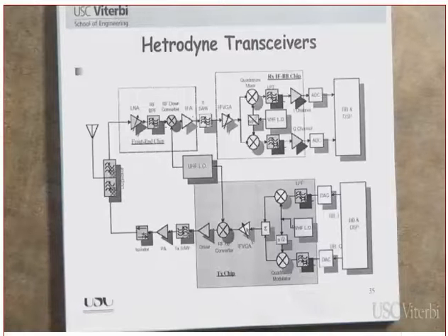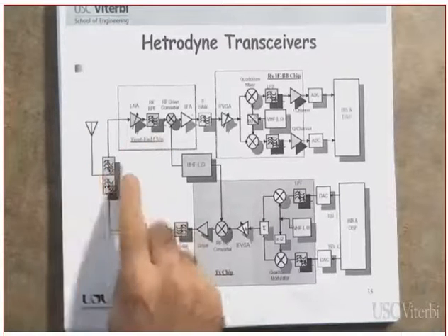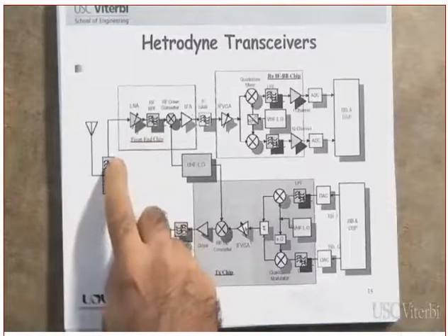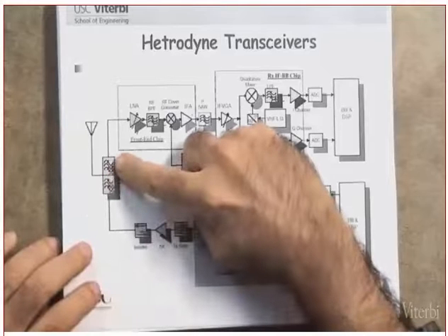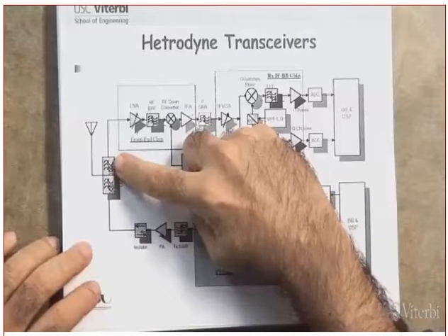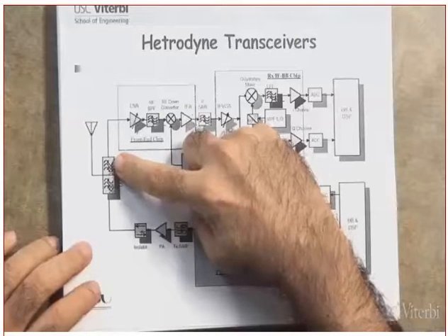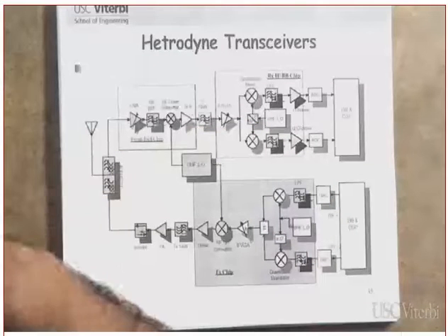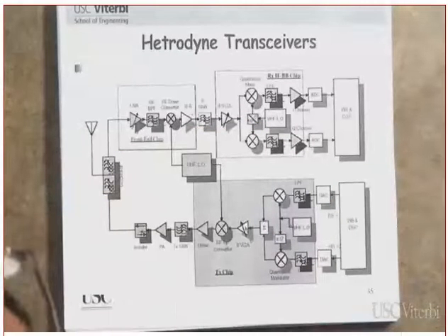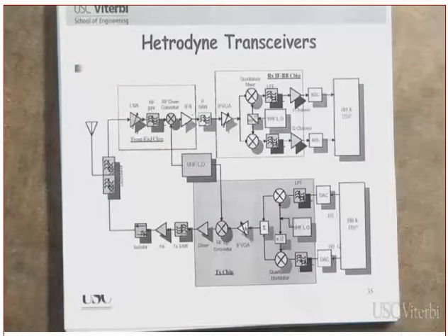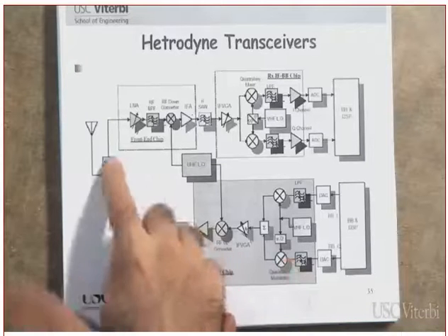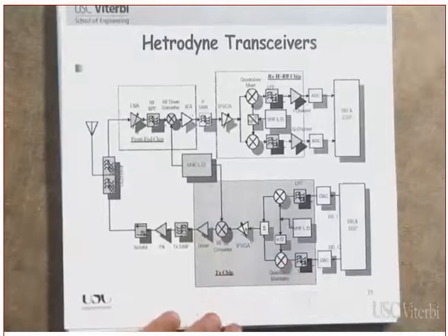The signal is received over the radio. What is this filter here doing? By the way, what type of filter is this? That's a bandpass filter. What is it doing? It is rejecting all out-of-band channels. Clear? It will pass all in-band channels.